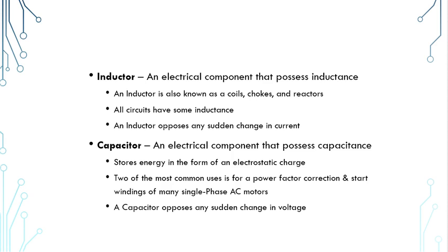Now, an inductor opposes any sudden change in current. So it works off of trying to keep the current as constant as it can. Of course, those 5 time constants we were talking about, they happen really quick. Now, you do have to watch out for an inductive kick. If you had a large wire a mile or so long and you remove the power on it, somebody at the other end goes to grab it, it would induce that voltage back and put them on the ground. And we call that inductive kick.